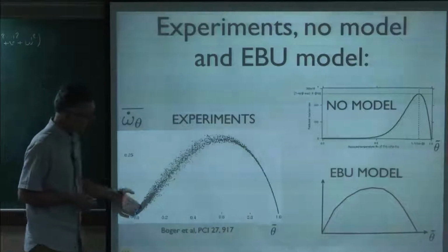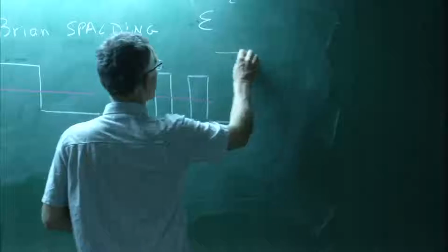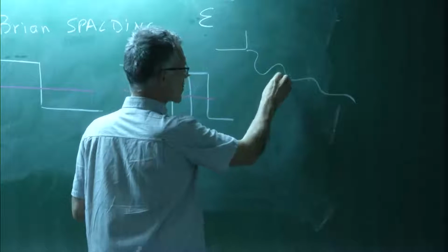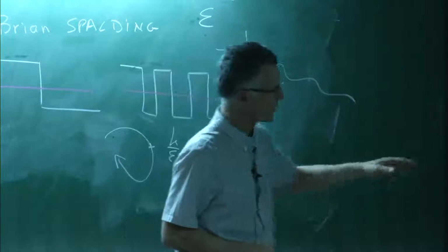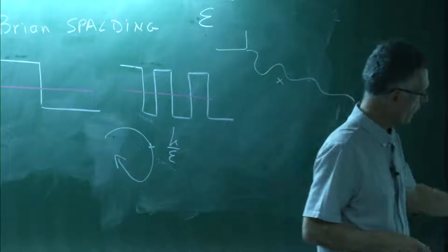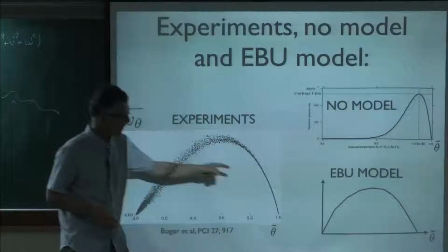You can take an experiment, a turbulent flame like this one, and go to one point and measure what we call the flame surface density, which is the reaction rate, the mean reaction rate. And this is the kind of curve you obtain. That's obtained from an experiment. And this is what the eddy breakup model gives.